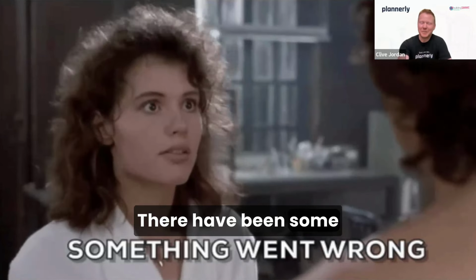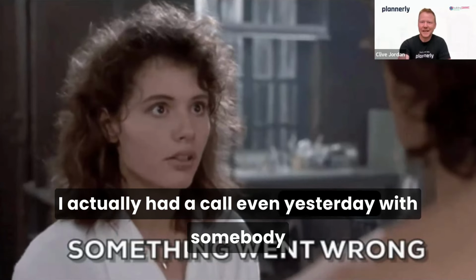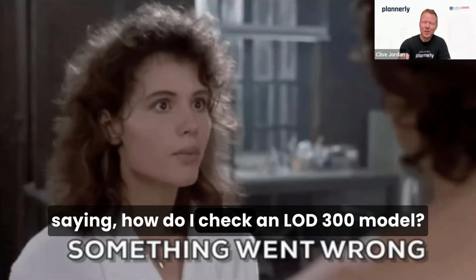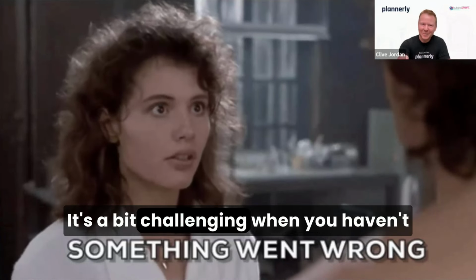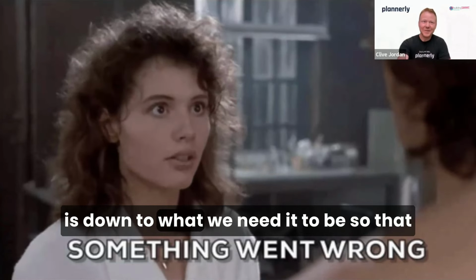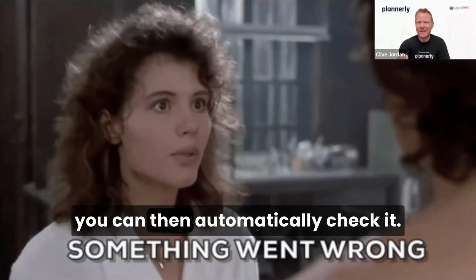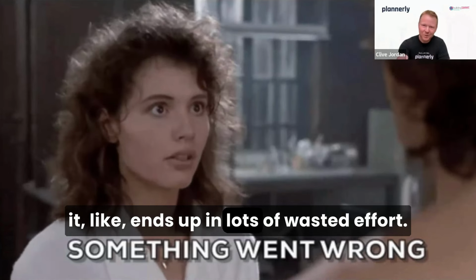Absolutely, yeah. There have been some really challenging situations. I actually had a call even yesterday with somebody saying, how do I check an LOD 300 model? It's a bit challenging when you haven't got the definition of really what that is down to what we need it to be, so that you can then automatically check it. So a lot of the time things go wrong. It ends up in lots of wasted effort.